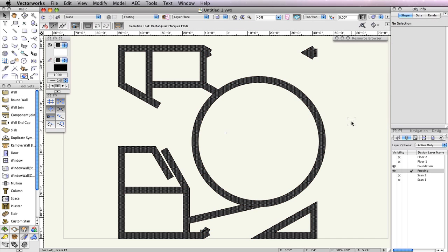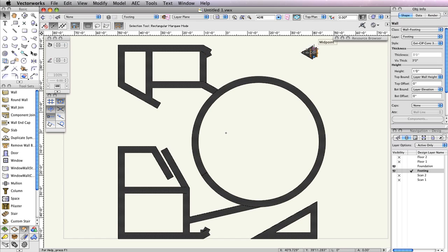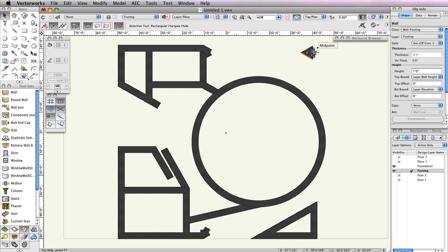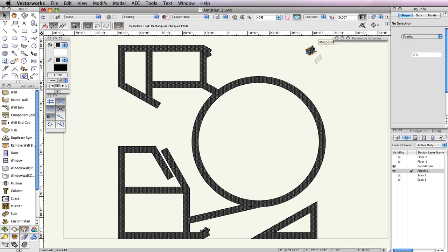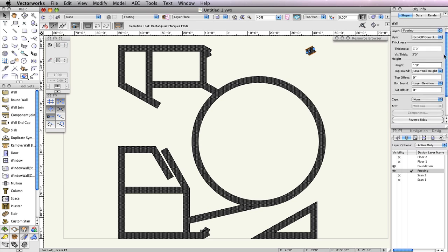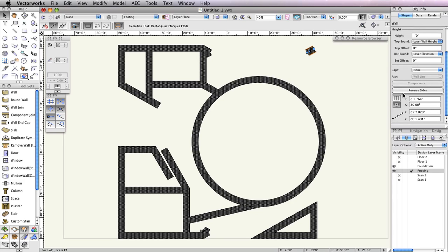Press the X key twice to switch to the selection tool, and deselect the current selection. Select one of the 3 walls. Then press the Delete key to remove it. Repeat this step again so that there is only one wall remaining. Now select the wall that remains and go to the Object Info palette. Click the Polar Grid button at the bottom. Next, choose the center position point and change the angle field to 180 degrees. Now the wall should sit horizontally.